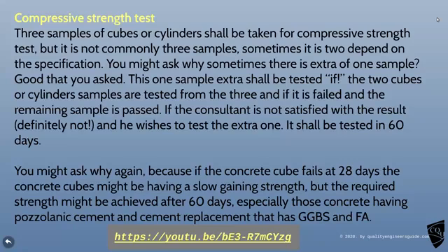You might ask again, because if the concrete fails at 28 days, it might have a slow gain in strength. But the required strength might be achieved after 60 days. But that should be evident in the engineer's design of the concrete.